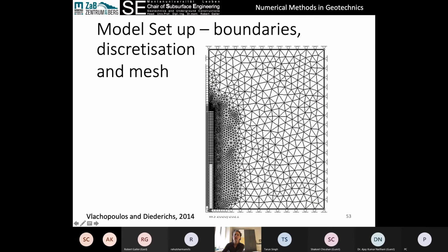And the face needs to be able to deform into the tunnel. So it needs to roll in this direction. And the reason I say roll is that the way that we visualize boundary conditions is using these little roller notations. So this roller is as though we had a bunch of pins or logs that allowed this material to move vertically. So it's rolling, and this material can move horizontally, again, as those rolling.